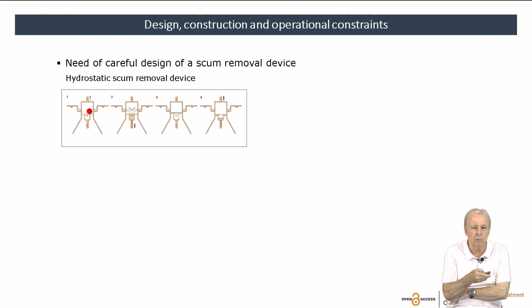We keep this gas chamber pressurized, so the scum layer will be here, close to the top of the collection channel. Then we release a valve outside the reactor, so there will be a pressure relief, and the scum layer will go up and go inside the gas chamber, inside the channel. Then after the scum is removed, we close this valve and the pressure is established here.